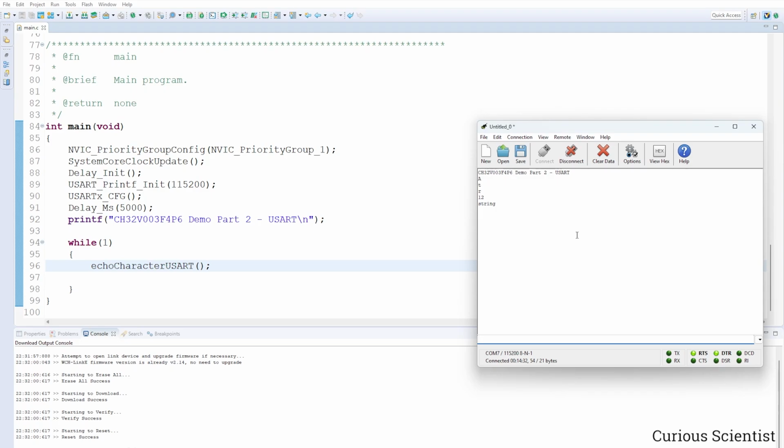Now I talk about the type, because we just rapidly sent back the individual characters. But this is not a string. This is basically 6 characters. How we can make sure that it does what it does is that, for example, I send a character, and if you look at the TX, RX, let's say, status lights, they will both blink. And if it was just a unidirectional communication, only one light would show up. But you see that both blink. So this works. So this is just that we can establish some kind of communication.